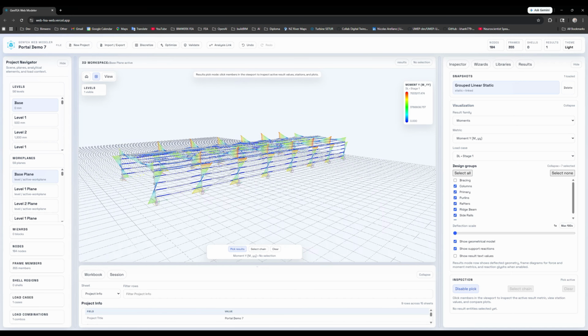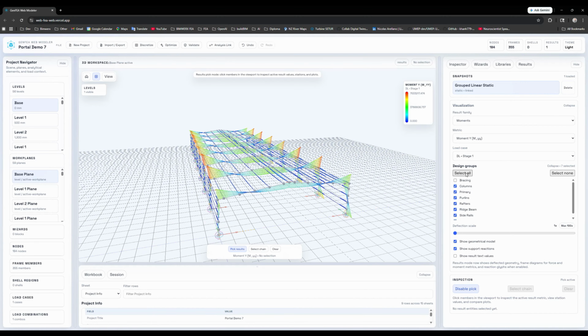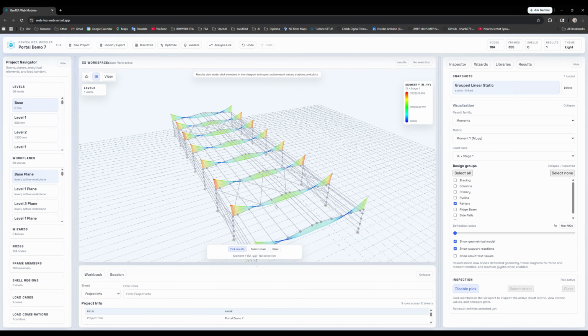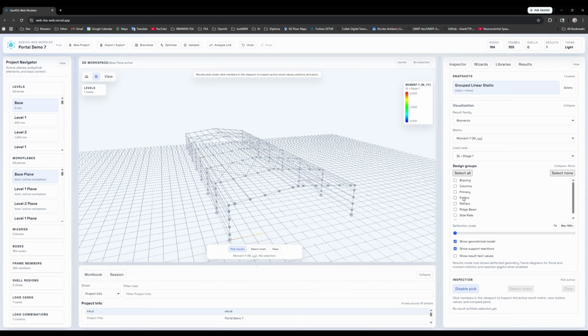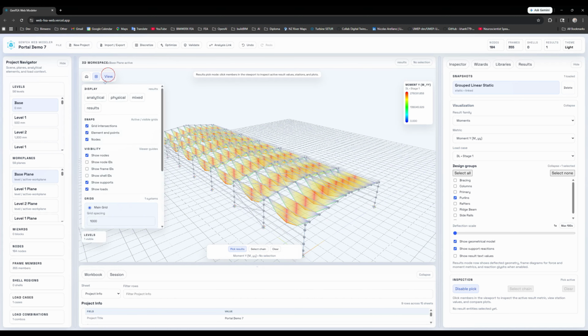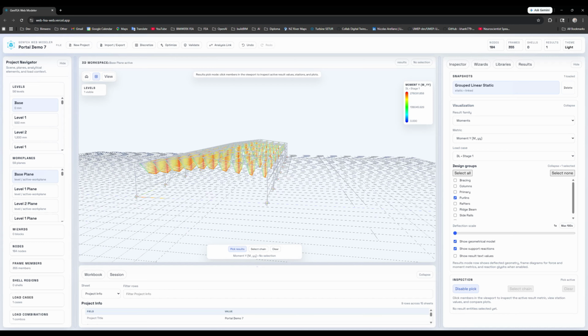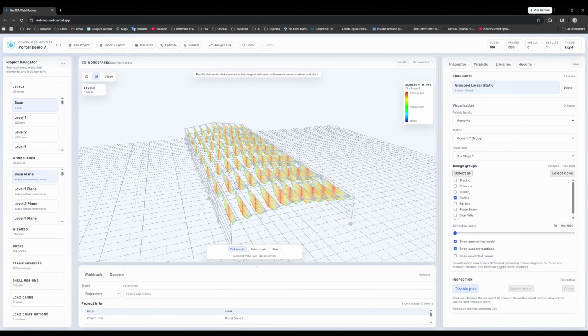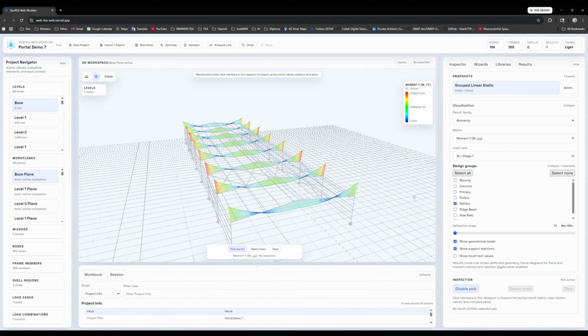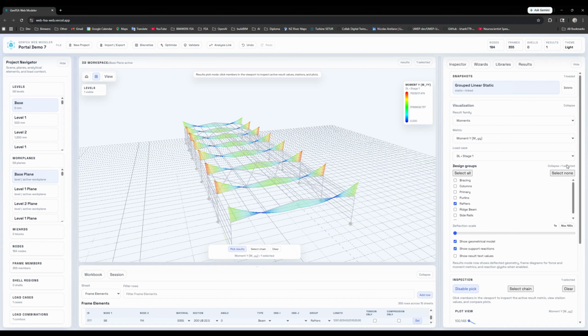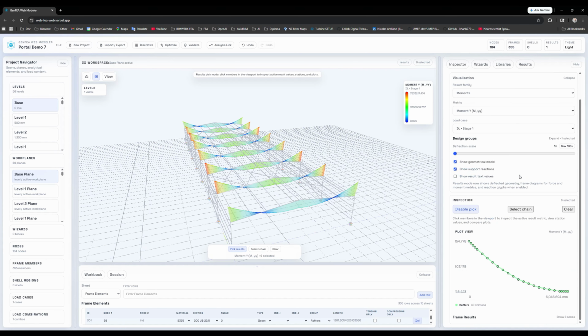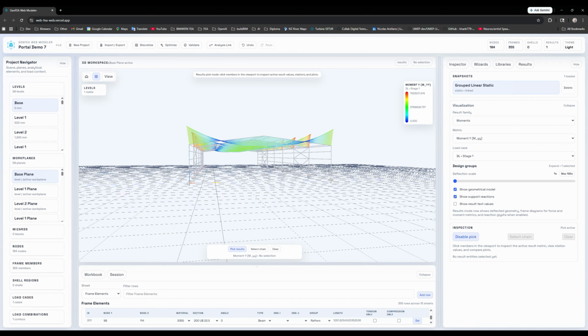And of course, just like I've shown in the other videos, we can select members here and plot the outputs of those elements directly in the graphical interface, or we can project that into the inspector on the right hand side. You can see those purlin moments are not transferring there because they're torsion pinned end members, by the way. But here you can see we're now selecting a chain of rafter elements to display that in the inspector.